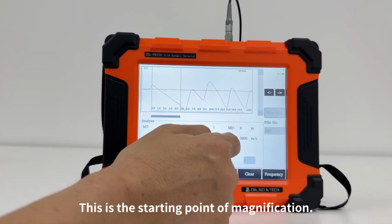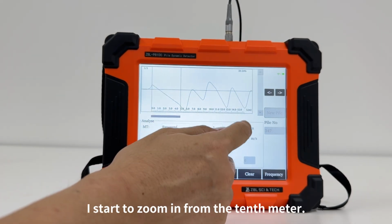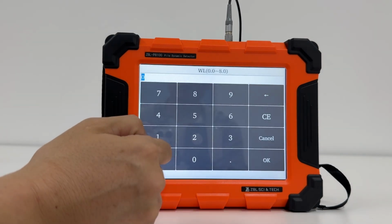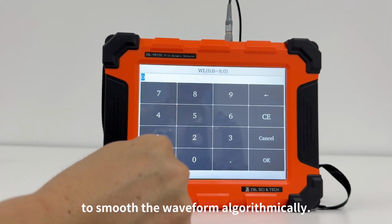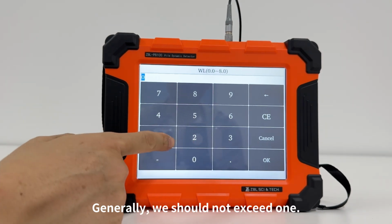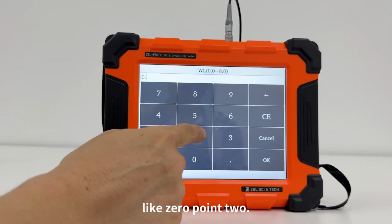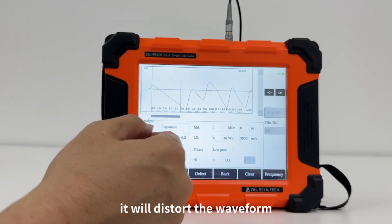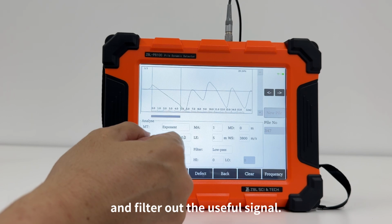This is the starting point of magnification. For example, if it's 15 meters, and the first 10 meters are fine, I start to zoom in from the 10th meter. This is the wavelet factor. The wavelet factor is to smooth the waveform algorithmically. Generally, we should not exceed 1, but use below 1, for example, like 0.2, because if you make the wavelet smoothing too high, it will distort the waveform and filter out the useful signal.